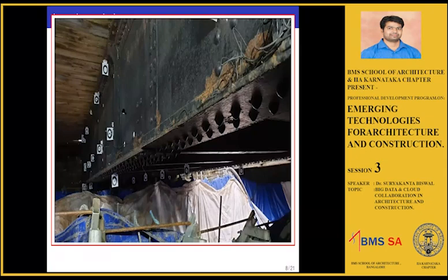This is the in-service testing that we did. Before removing the bridge, we went to the site and took some measurements. This is a video gauge-based measurement, a contactless measurement. We had targets and a video camera somewhere here. As the train passes, the bridge will deflect. We measured the deflection of the bridge, the main girder and the cross girder, under the train load.